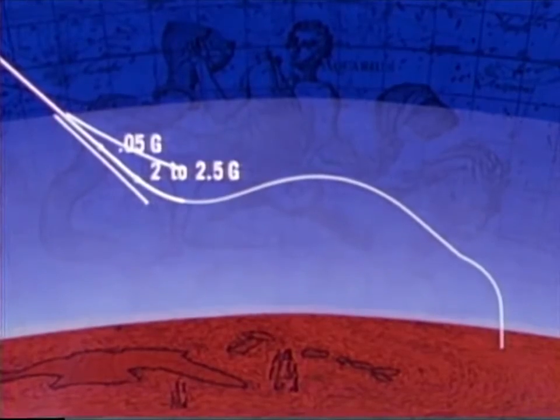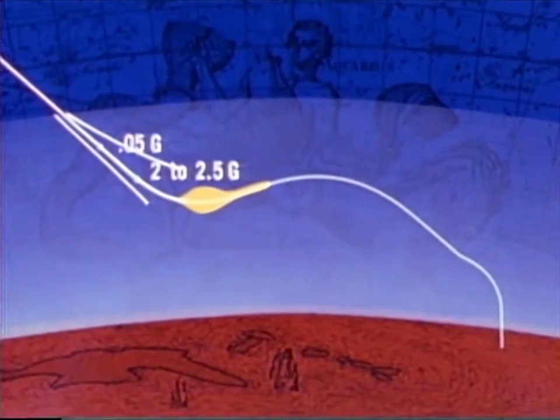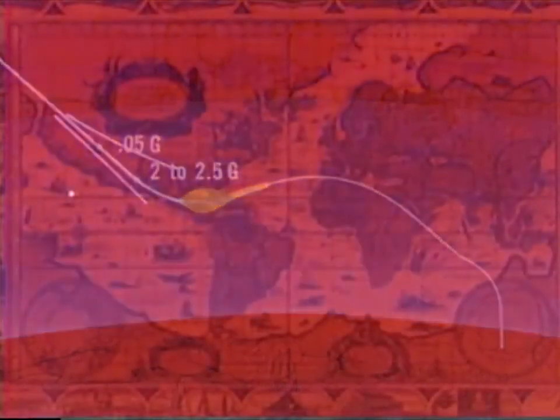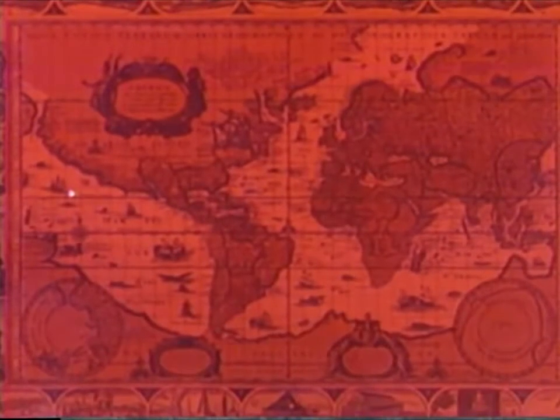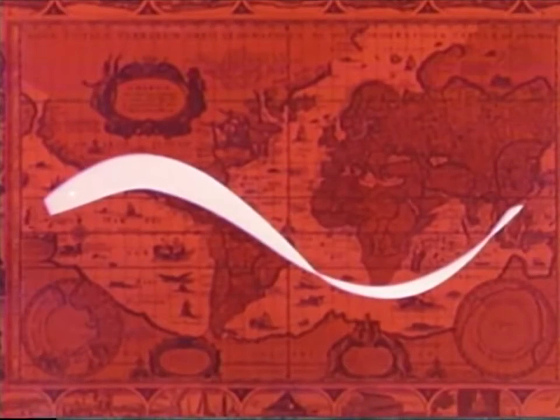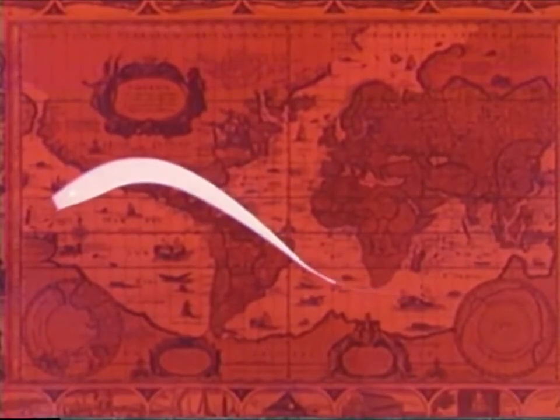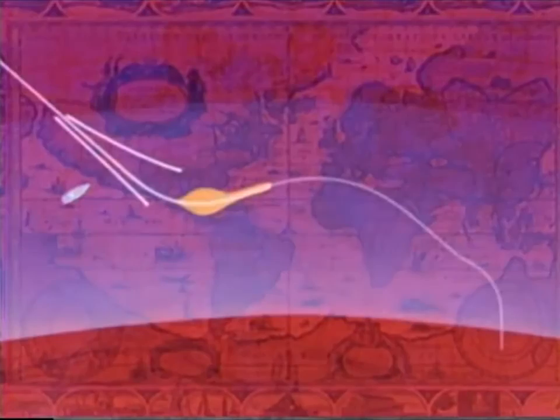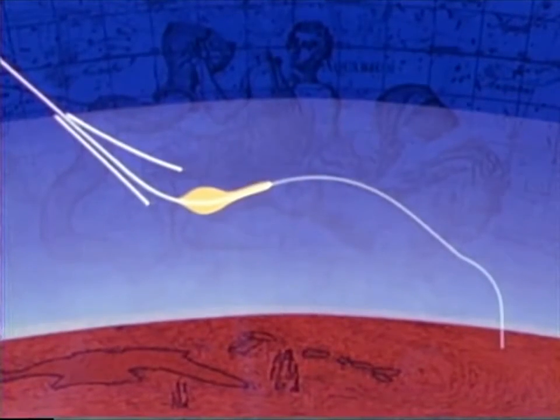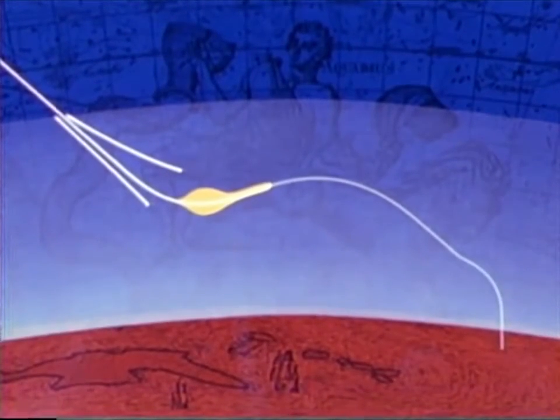Just before pull-up, the first control period will begin. During the first critical 70 seconds of this control period, the initial landing footprint, 20,700 miles in length, will be shrunk around the target to this 2,070-mile footprint. In the remainder of this first control period, the footprint will shrink further to this 690-mile-long area. The first control period is followed by the controlled skip.